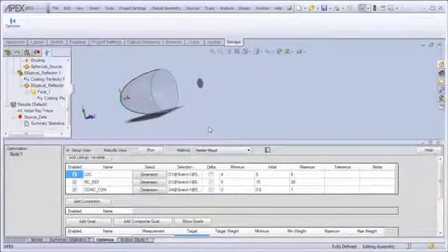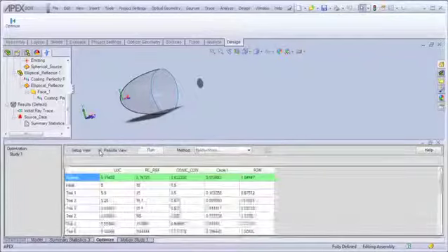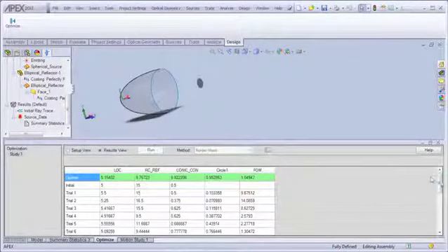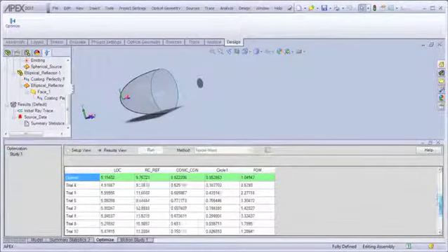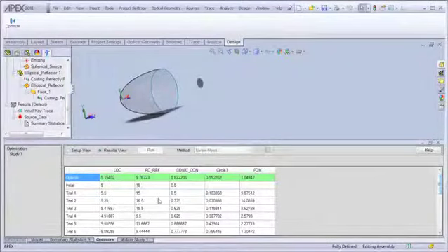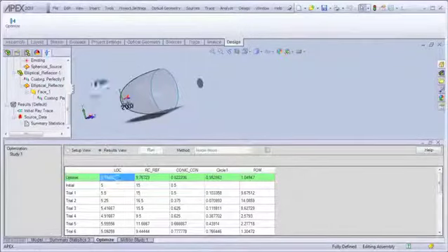When you are ready to view results, press the Results View radio button, and you will see your trial solutions listed along with the various variable parameters and the figure of merit. At the top, highlighted in green, is the optimal solution. And if you click on that, Apex will automatically set your geometry to that optimal solution.